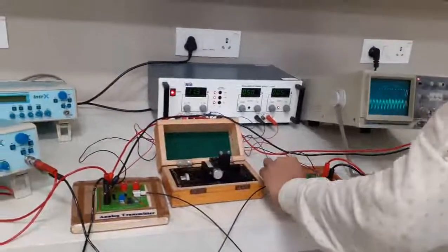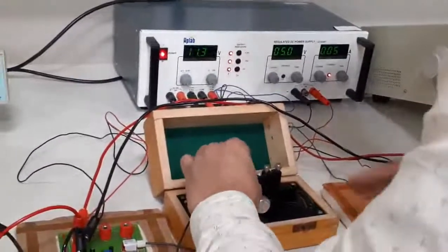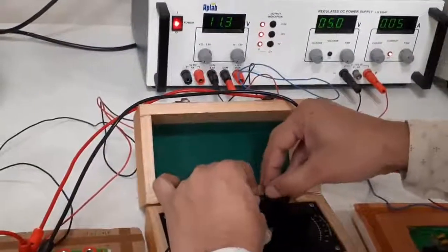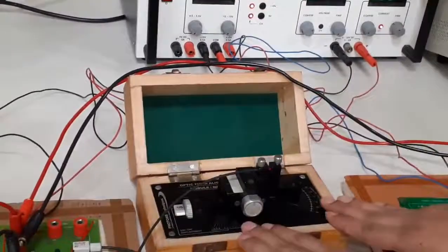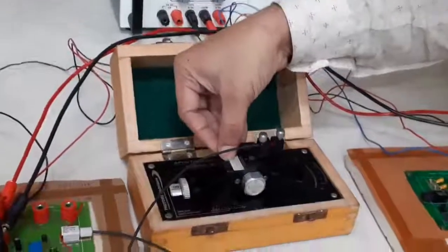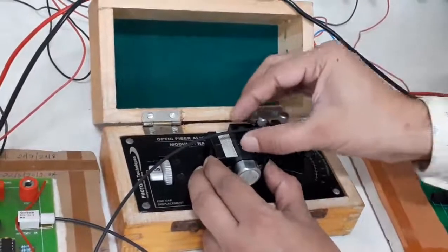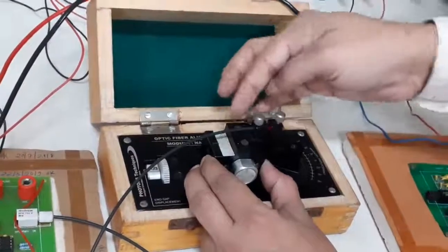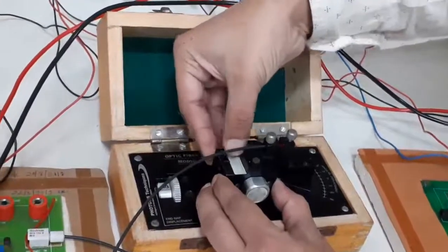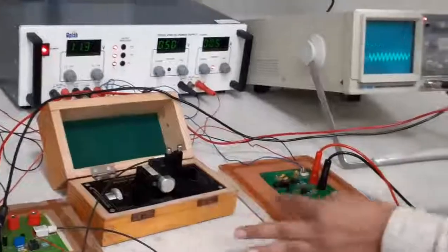So what I am going to do now is couple this optical power into the module, and I will press down this screw so that I have set this module at its default values. In the center, there are two modules, one is this and the second. The centers of both are aligned by means of a central line. If you are able to observe here, a notch is given. That notch is maintained. So for lateral displacement, we are going to connect one fiber here and a second fiber from this end to the other end.